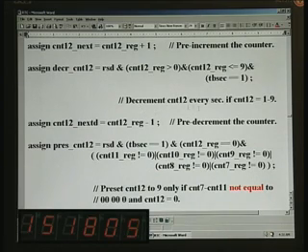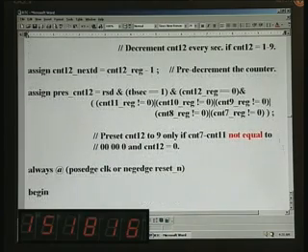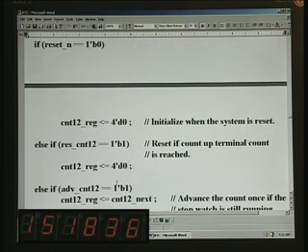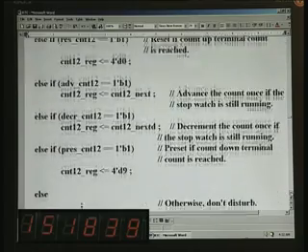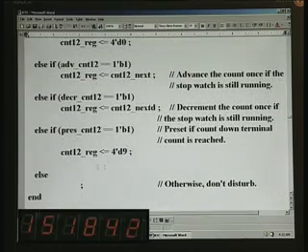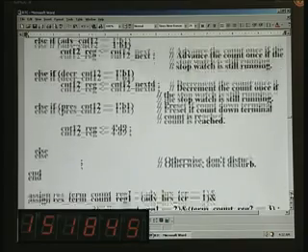in which case counter 12 is decremented every second only if counter 12 is 1 to 9. So, 1 can become 0, 9 can become 8, and so on. And once again pre-decrement and preset the counter, and this happens only if counter 7 to 11 is not equal to all zeros. Counter 12 also must be equal to 0, and it is preset to 9 in this case. So, this block for counter 12 is this, precisely the preset is that 9 will be reflected here, and all the other things are similar.